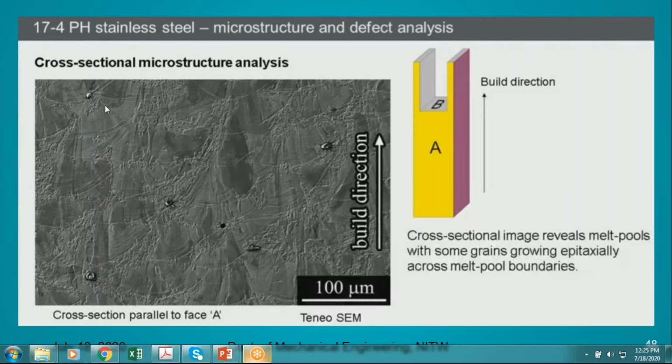For each successive layer, you get successive solidification rates and solidification profiles. Where the solidification interaction takes place between the successive layers, the interfusion of the successive layers depends on the strategy which we are using. Where this interaction takes place, you are going to have unmelted particles, or porosities may occur, these types of defects in the fabricated components.